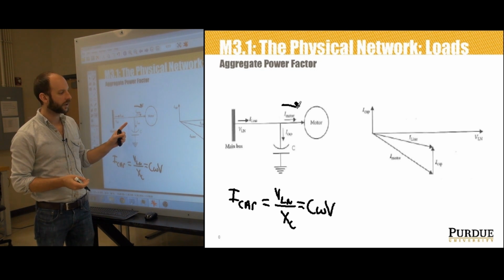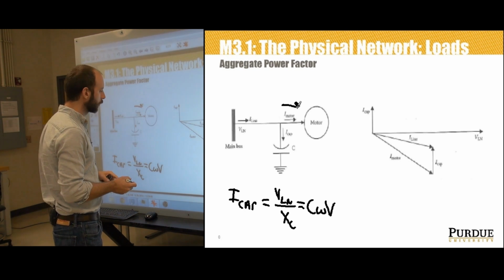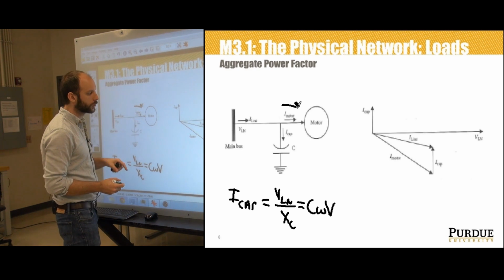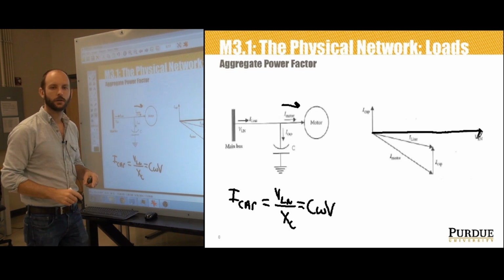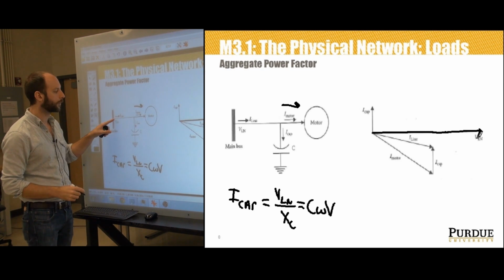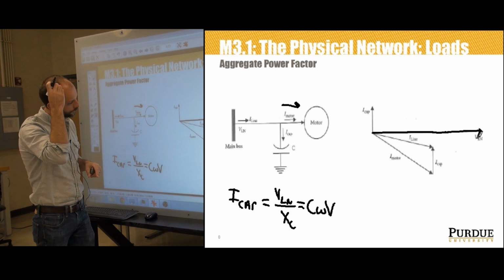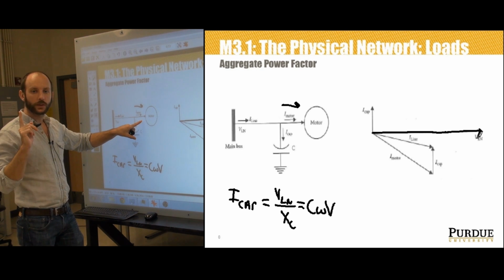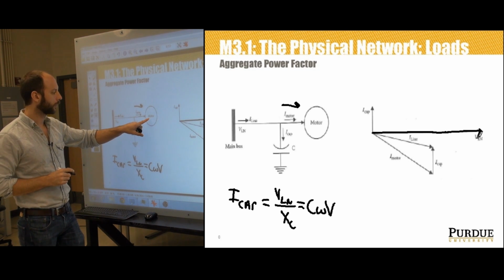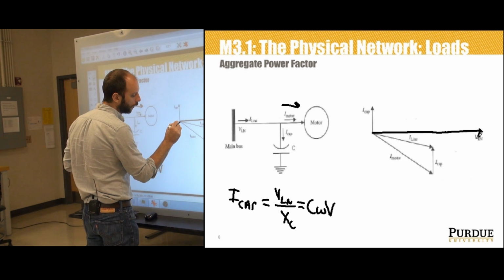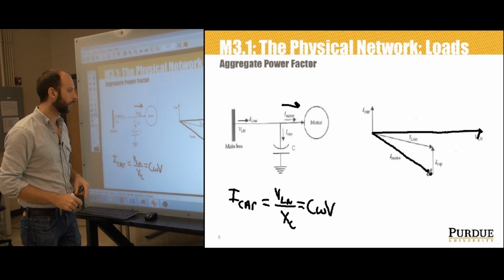And we can see this best on the phasor diagram. So the first thing we're going to do is draw the original motor current. We've got the line voltage drawn here in black. That represents the voltage at the bus. We know that when we only consider the current draw of the motor load, it's going to be in the fourth quadrant because it's a resistive and inductive circuit. So we're just going to draw the current as some generic phasor in the fourth quadrant.